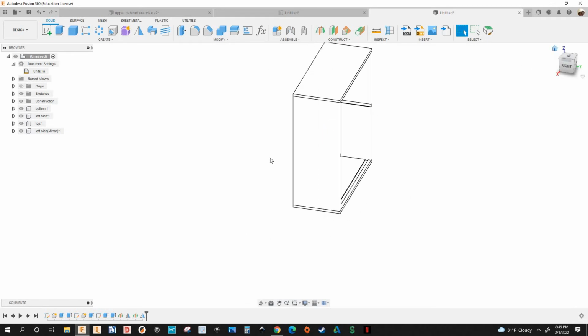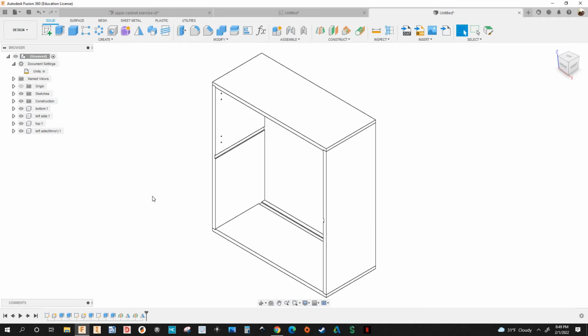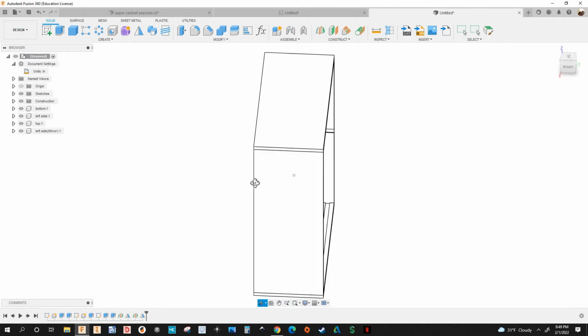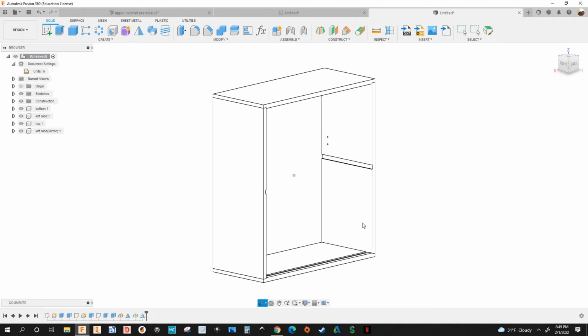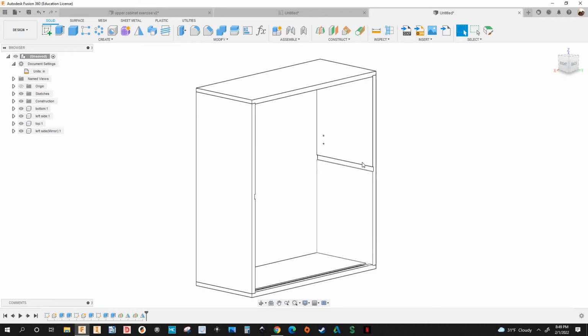All right. Next, I'm gonna create the back panel, but I'm missing that groove here for the back panel. This is 28. Okay, so I'm gonna have to create a new sketch here. Okay, do this again. All right. I can delete. Go back to that